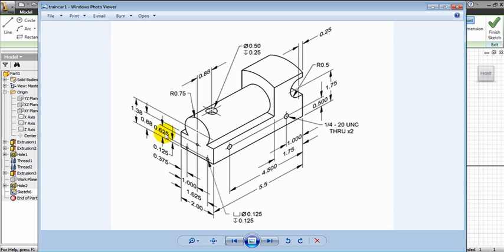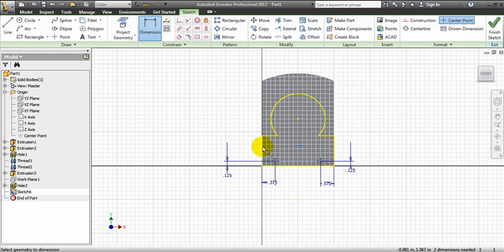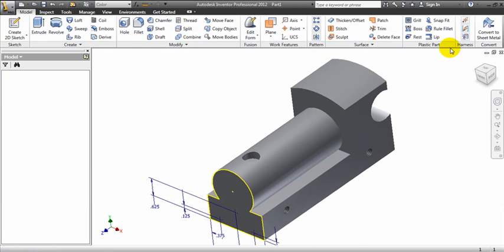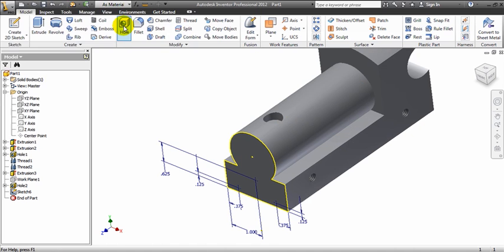The third one is 0.625 because I'm looking at these 2 arrows which are telling me the distance between this line right here and the base. 0.625, and this thing is right in the middle, so it's 1 inch in the middle. 0.625 and 1. To here is 1. And from here to the base, 0.625. It's important that you make these in the right place, as well as the cow catcher correctly, because these need to fit in perfectly. So I'm going to hit finish sketch, and I'm going to grab my hole tool, and